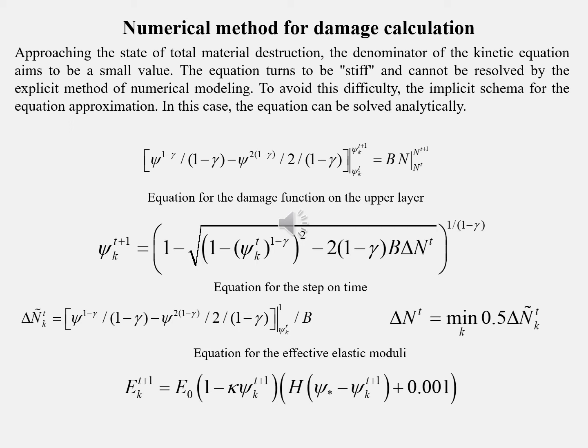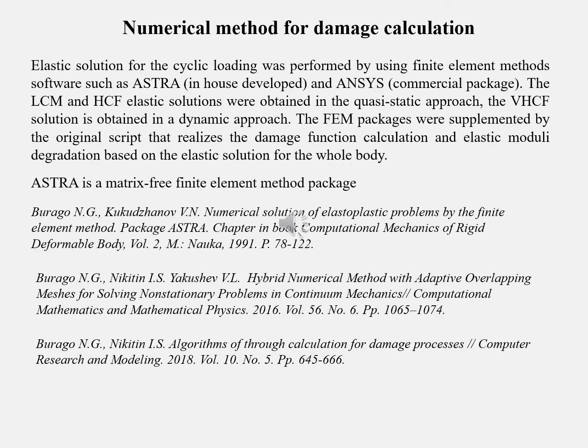Here we have some limitation for the step in number of cycles. We use a half of it, and below it is written the equation for the Young's modulus as a function of the damage value. The numerical method is as follows. First, we obtain the elastic solution or elastic-plastic solution for the problem by using one of the packages that perform the finite element method.